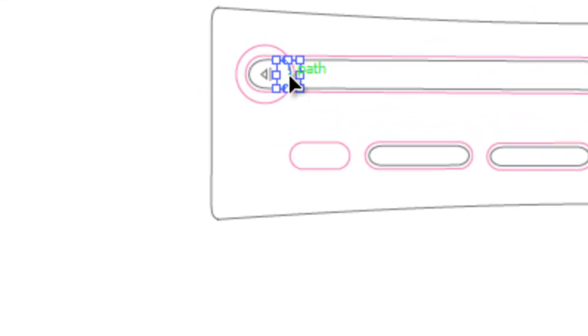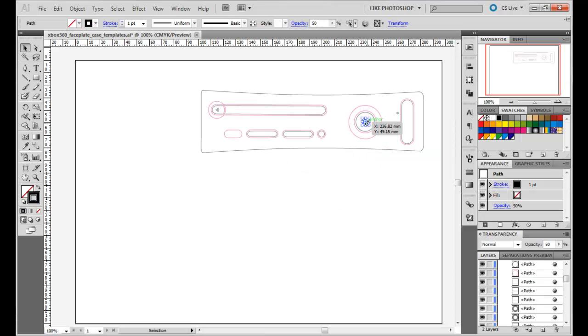You will notice that the closed path in the bottom left portion of the faceplate is magenta. Unlike the other magenta paths, it has no corresponding interior closed path that is stroked with black. I am directing the printer to eliminate the complete interior of this closed path from the faceplate. I define the remaining cutout paths.